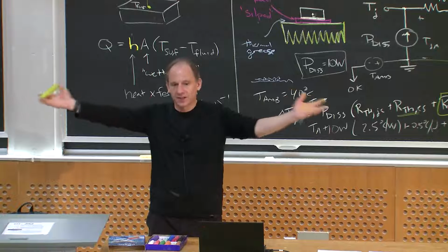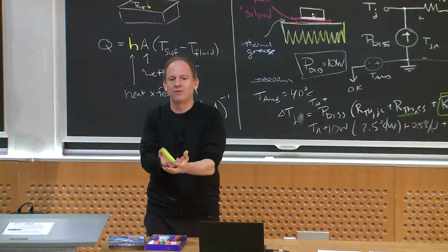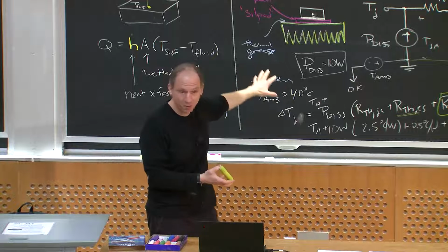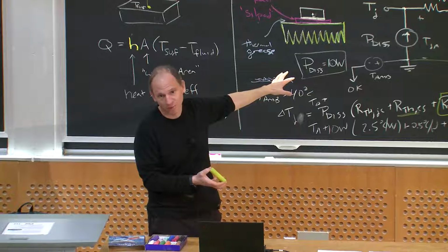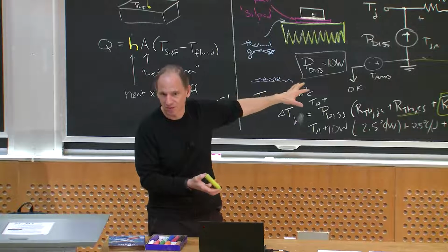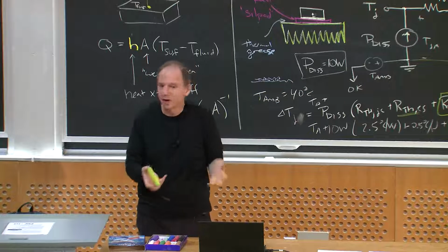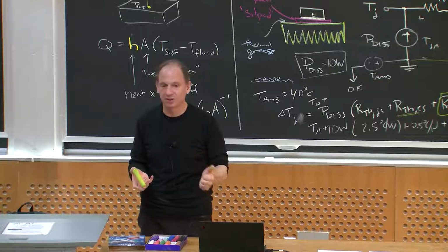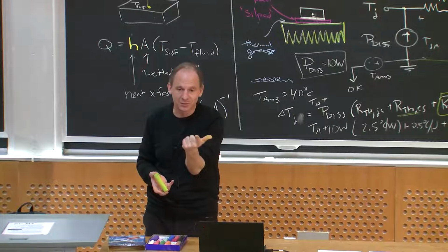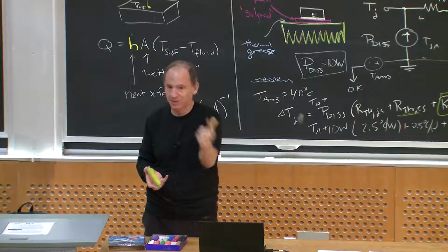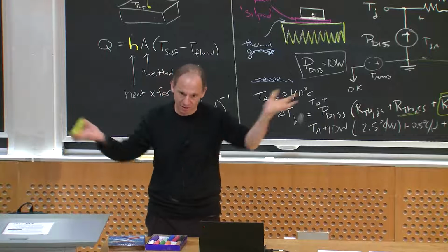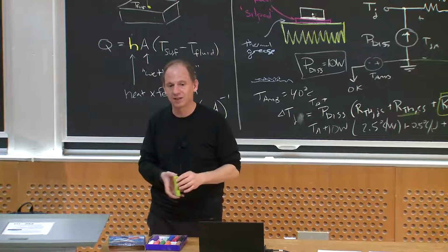At a broader scale, if you have to consider the whole thermal design, either you get a bigger network or you start to pull out computational tools like finite element tools. But very often for a power converter design, in a buck converter, you might have your MOSFET and your diode as being big sources of loss, and then maybe your inductor is next. And you just model those into the system and figure out how you're going to heat sink it.